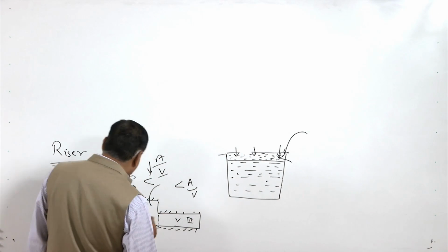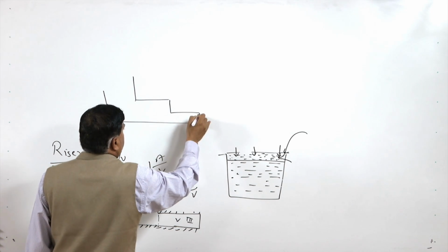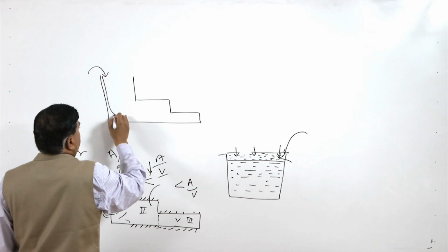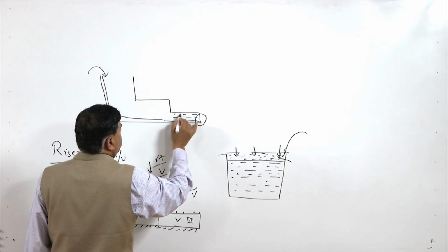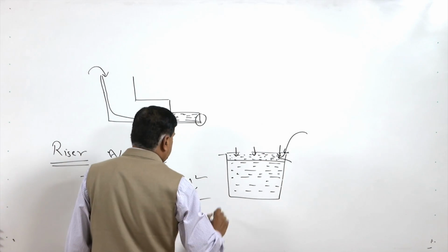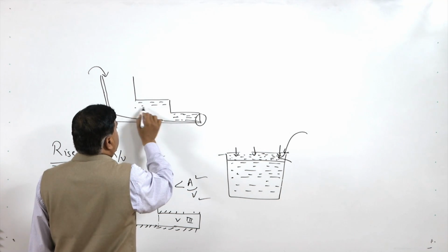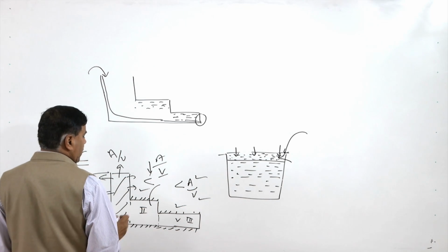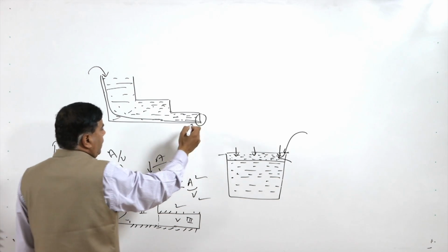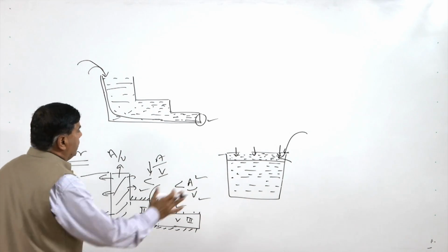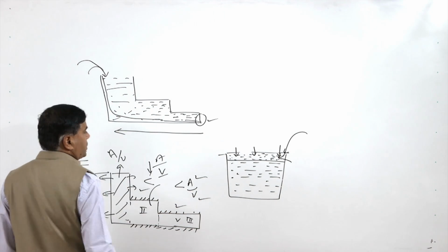So, in this case if we are feeding the molten metal in this mold, the mold is of this kind, where the molten metal is being fed say from the top. So, the molten metal will be reaching to this zone. This is the remotest zone from the feeder. So, this zone is expected to solidify first because of the higher surface area to the volume ratio. So, solidification will start here and then it will be progressing. It will be starting from this zone 3, then it will be progressing towards the zone 2 and then zone 1. So, in this case, since the solidification starts from the remotest point from the feeder, it will then be approaching towards the feeder.